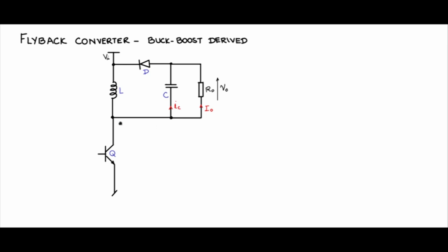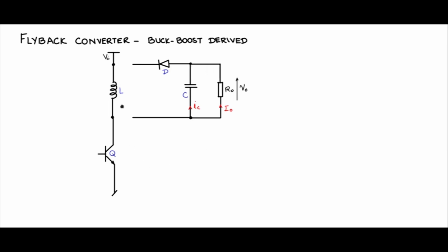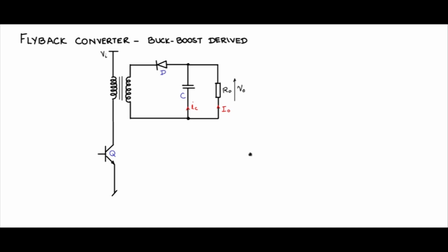This portion of the circuit, we will push it out and introduce isolation here. Observe that this is an inductor, and we are winding one more winding on the inductor so that it provides isolation. But the behavior of this magnetic will still be inductor energy storage. So let us put in one more coil there. Let me make some space arrangements. Put in the core and put in the secondary coil, and then connect it in this fashion.